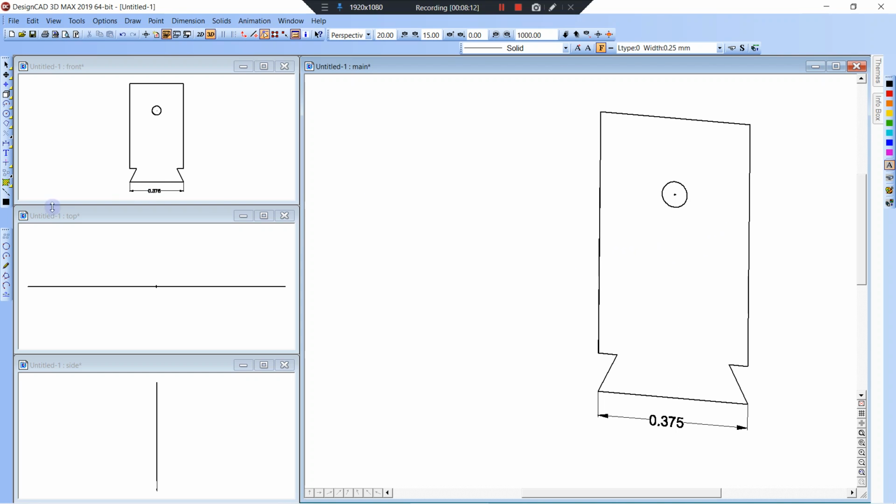And what I like to do is create a rectangle, cube. So to do that, you go to rectangle and then insert a point anywhere, and then Control Shift at the same time, and you can stretch it one way or the other. So Control Shift, and I'm going to do it like that. Put that there. All right, so now I can see what the solid looks like.